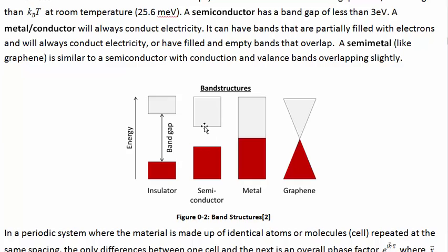There's some kind of a gap called the energy gap between where the charge carriers are and where they need to be for them to conduct. In an insulator, we've got the same situation, but the band gap is very wide. So in a semiconductor at room temperature, you may have thermal excitations prompting some electrons from here, called the valence band, up here to the conduction band, where they can then move under the influence of an electric field.